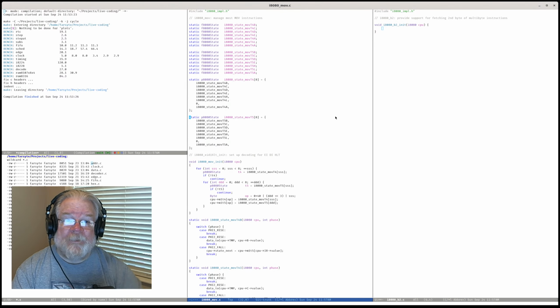Now the next one is PC Inc, which we are now calling here. This comment is wrong. State PC Inc, nsync, start dbin, check ready. So increment the PC, we end the sync, we release the data bus, and we start dbin, and we check ready.